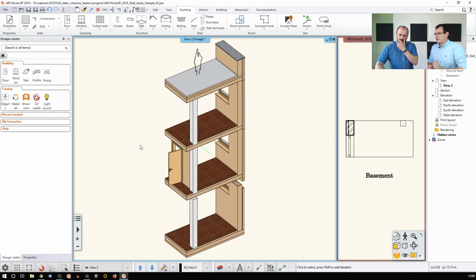The question: what kind of elements can be bound to these levels? I know that slabs can be, and columns. Slabs, walls, columns. Most of the structure can be bound like this, because this keeps the workflow easy, and you don't have to manually specify changes one by one, or copy properties, or any other way. You can just solve this on the global scale of this building.